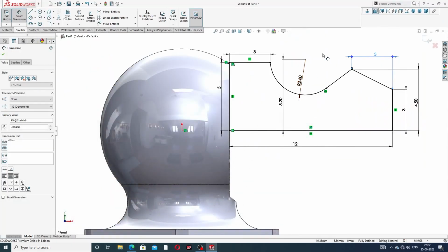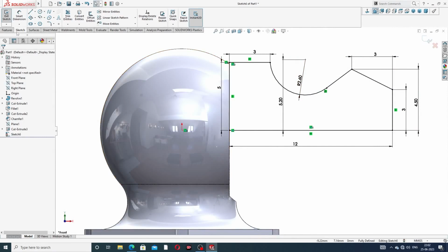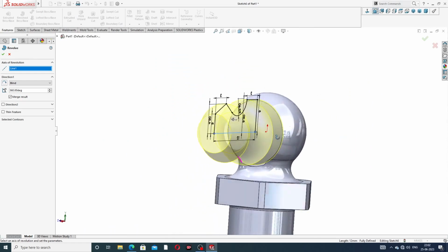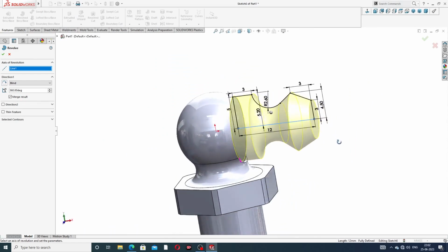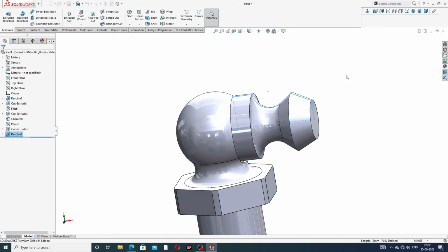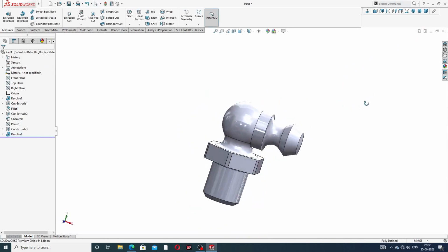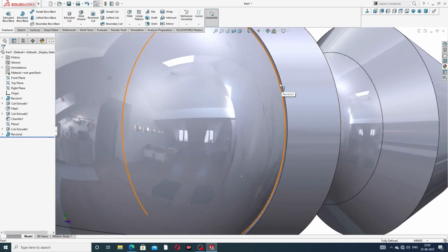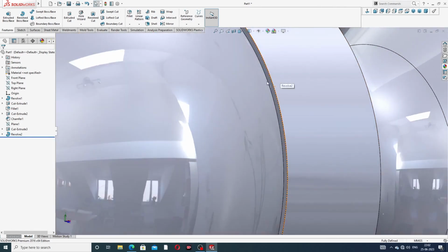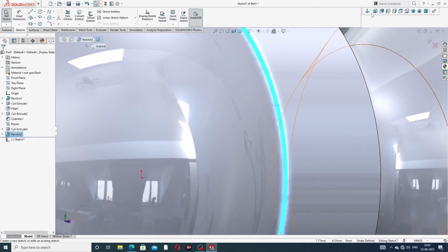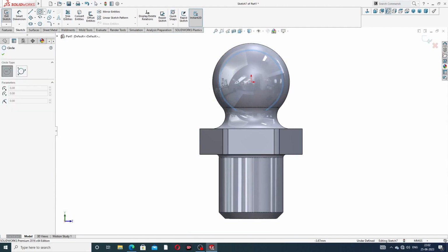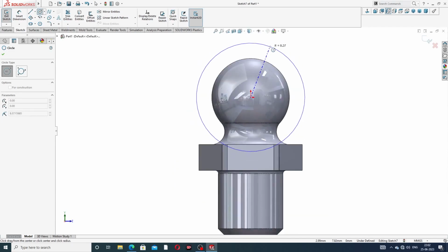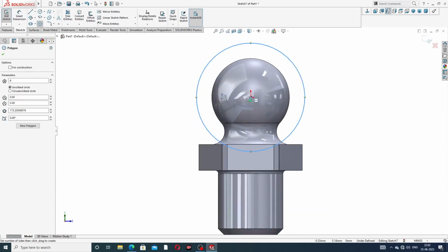Okay, and click revolve boss base and click this. Okay, all is perfect. Looking here, click OK. But some points are very important. This face, sketch here, sketch normal, draw a hexagon. Okay, draw a circle, a big circle, and also draw a hexagon.